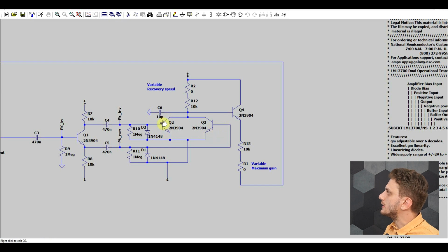These are detected by the two transistors, so Q2 and Q3, and basically these provide our peak detector with the threshold voltage, 0.6 volts for the base emitter voltage. So if either of the two signals is large enough to polarize the transistor, then the collector will be pulled to ground. And now the voltage potential of the collector of these two transistors is responsible for driving the final transistor, which in turn is providing our voltage to the first circuit, so to provide the negative feedback to the